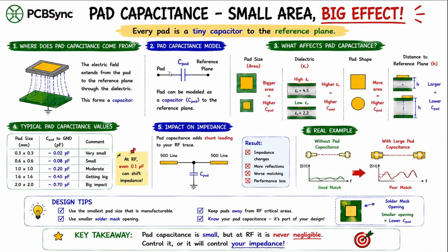Digital engineers like things big. Big traces give them a sense of security, but when RF engineers see a big pad, they often get nervous because underneath, the ground plane naturally forms a capacitor. The larger the area of the pad, the greater the capacitance. Don't underestimate the impact of this at certain frequencies. It can totally throw things off. So, when it comes to pad design in RF, the rule is simple: just make it big enough, don't overdo it.